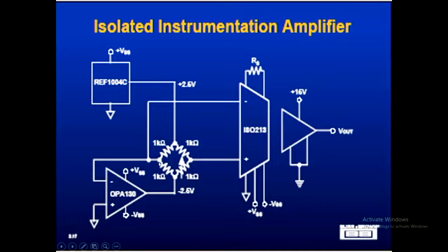And are you good with 2.5 milliamps being confined to flow down there? Yeah? So we've got 2.5 milliamps flowing across this resistor, and it's a 1k ohm resistor. What voltage is set up? What voltage will 2.5 milliamps through a 1k resistor provide? 2.5 volts, okay.